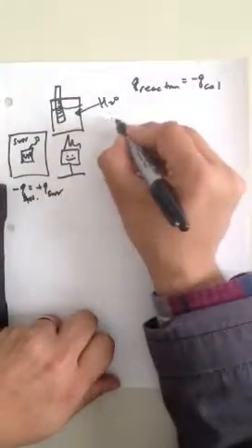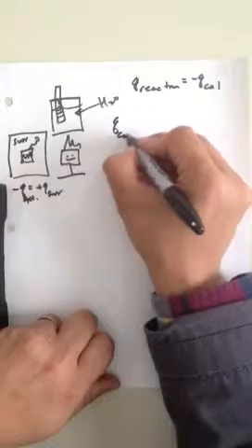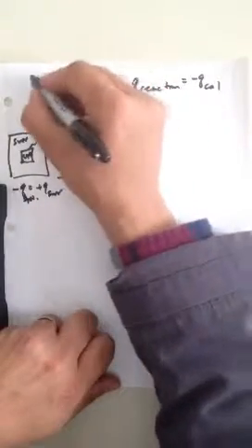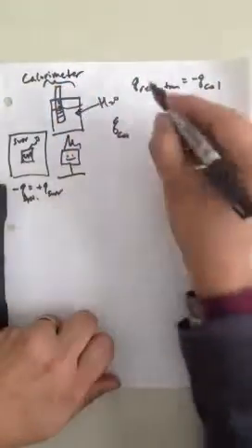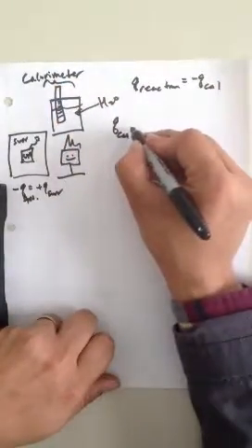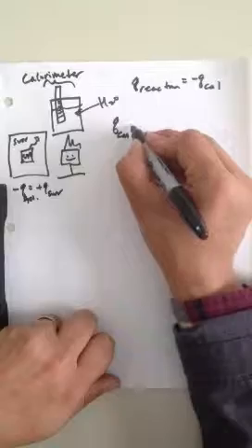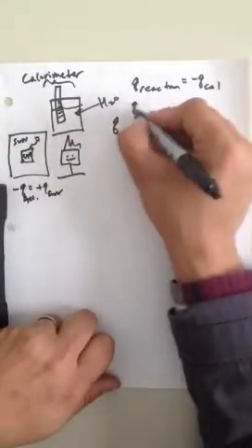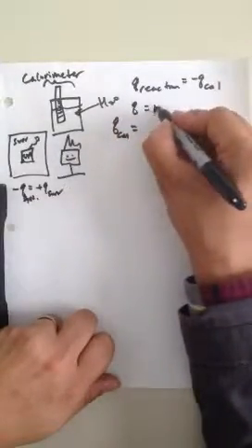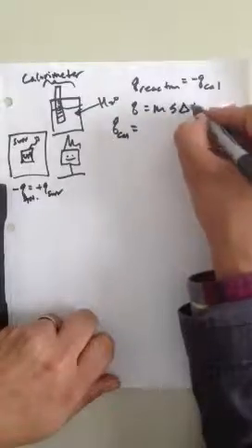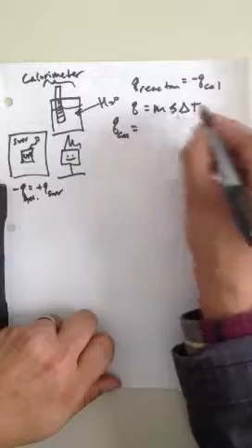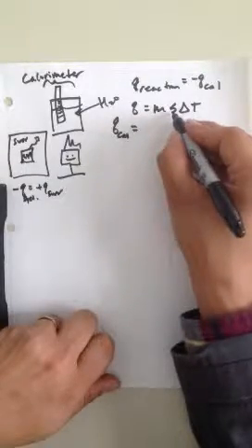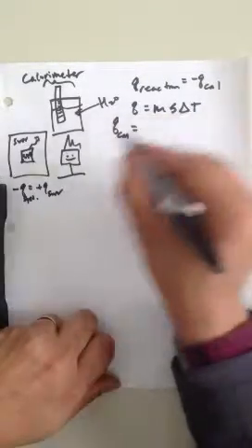The equation for the heat of our calorimeter, that's what this guy is called, because it measures heat in the form of calories, although we're using joules because we're awesome. The equation for all heat flow is going to be Q = msΔT. In this case, remember, m is the mass of the substance, S is the specific heat of the substance, and ΔT is the change in temperature.